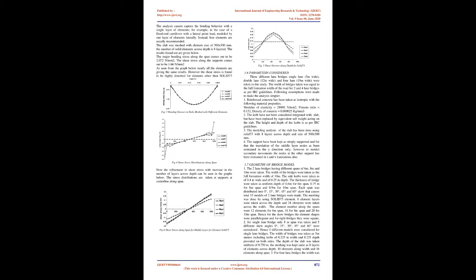The element is defined by 20 nodes having 3 degrees of freedom per node, translations in the nodal x, y, and z directions. SOLID 186 may have any spatial orientation. The element supports plasticity, hyperelasticity, creep, stress stiffening, large deflection, and large strain capabilities. It also has mixed formulation capability for simulating deformations of nearly incompressible elastoplastic materials, and fully incompressible hyperelastic materials.